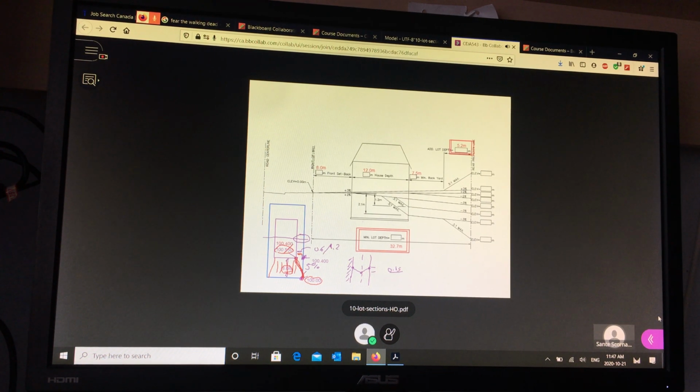That's 5% up from the corner of the lot at the front to the corner of the house. Then I'm going to come down, right? I've just designed this elevation here. Look at the cross section. I've got this elevation here now. What's the elevation at the opposite corner on the lot line? What's this elevation going to be?